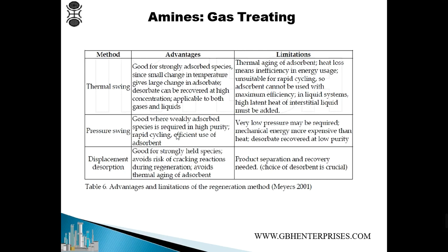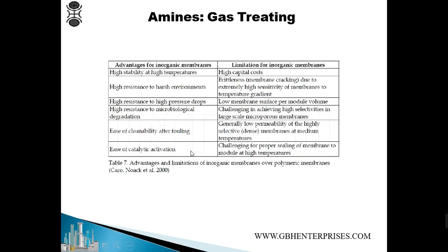In the pressure swing one, a low pressure is required, but it needs mechanical energy, which is more expensive. So it is quite expensive. The pressure swing one is less common, and the thermal swing one is the most common one that we use here.